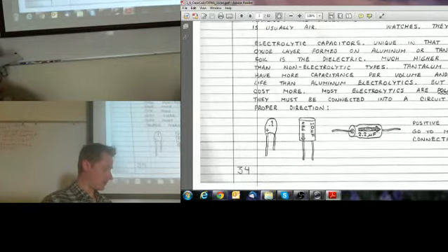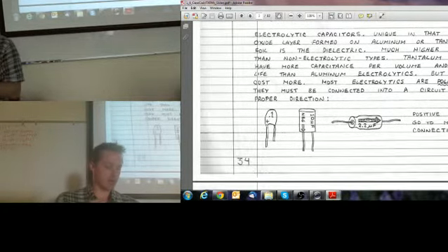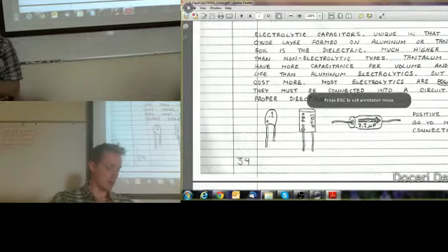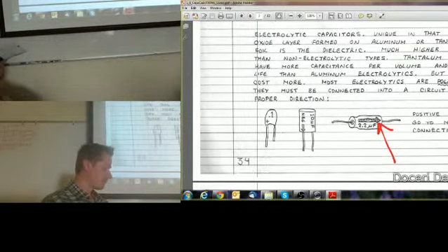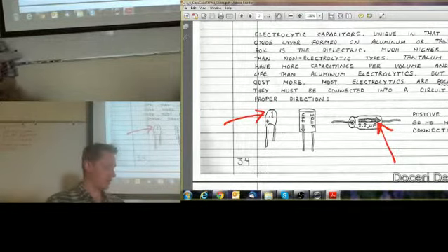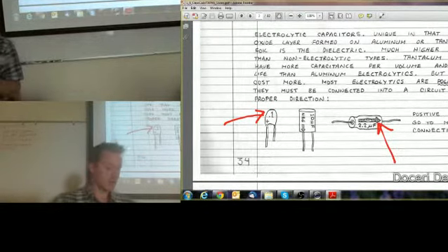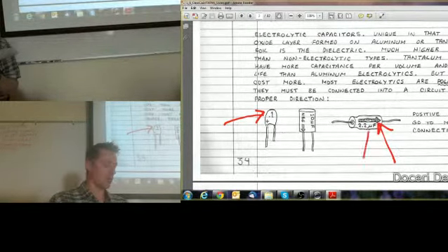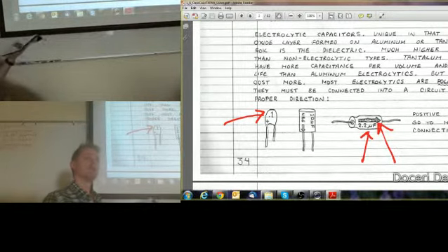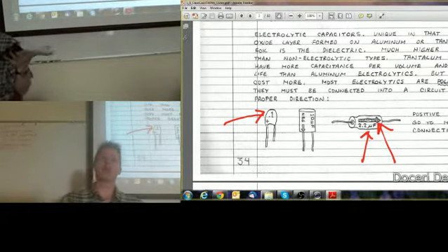And yeah, do take note that electrolytic capacitors are going to be polarized. They have this indicator on them to show you where the minus terminal is at. Like a ceramic capacitor will have a marking 0.1. Now the electrolytic capacitors normally are marked in microfarads. All other capacitors are always marked in picofarads.